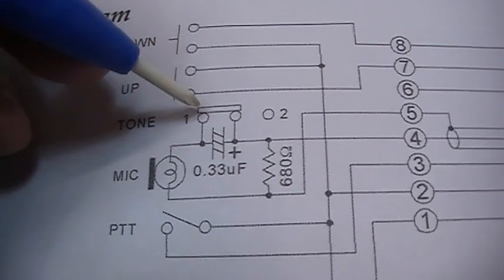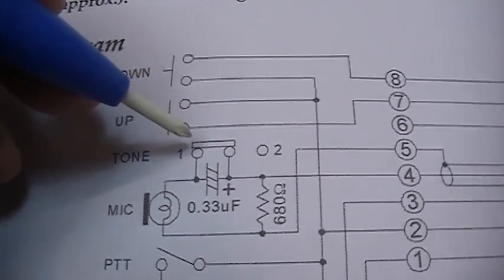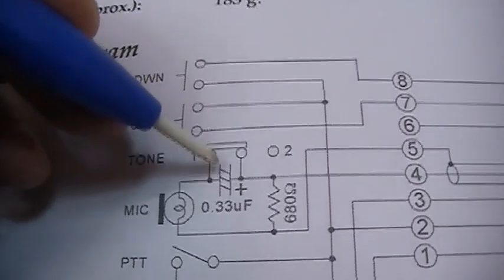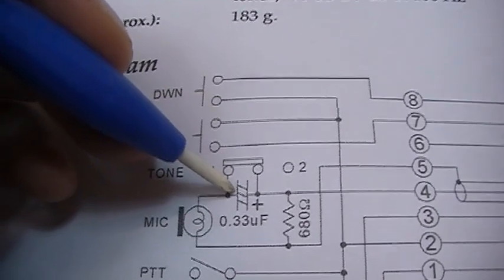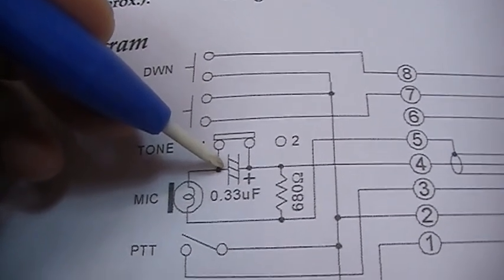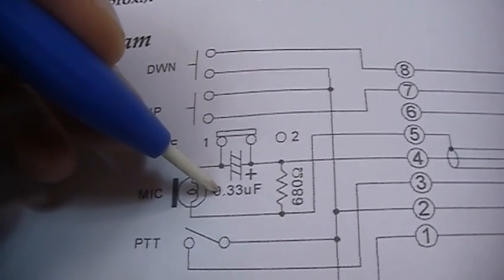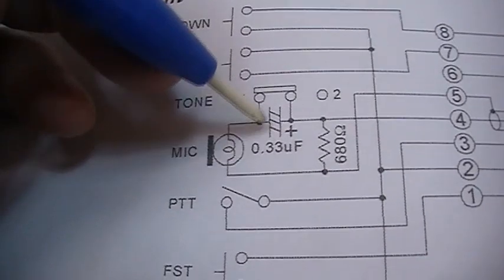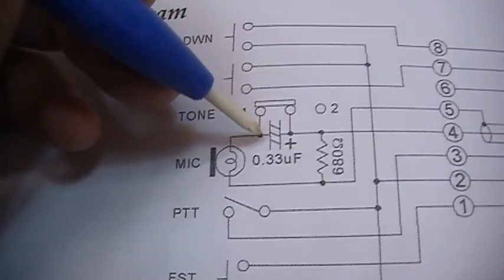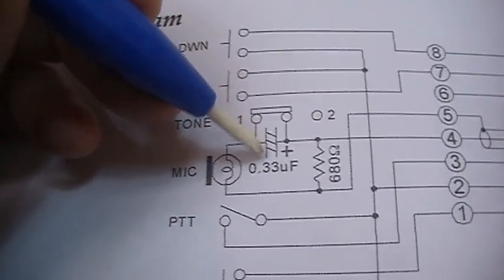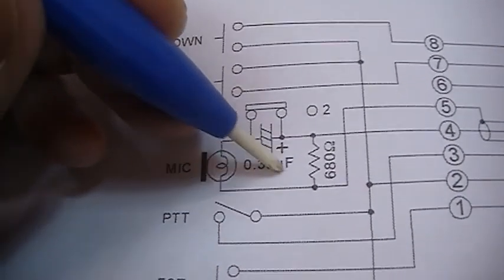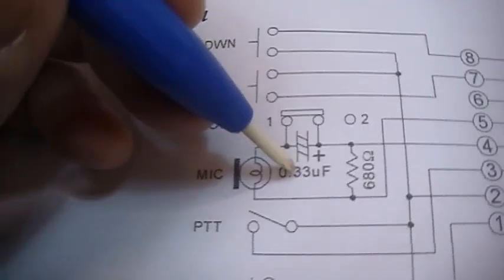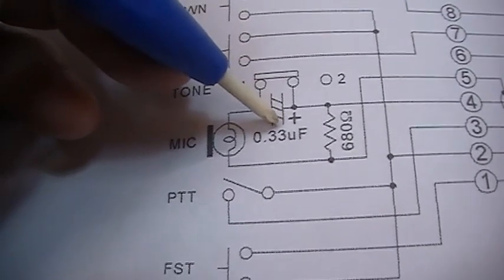I would go and try for 47 nanofarad, because then we have 2 different tone variations for the different bands. So the 0.33 microfarad would be the switch position for FM, because with this bigger capacity you have more bass in your modulated signal.